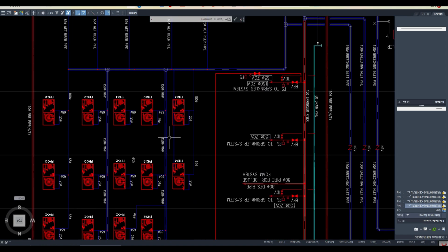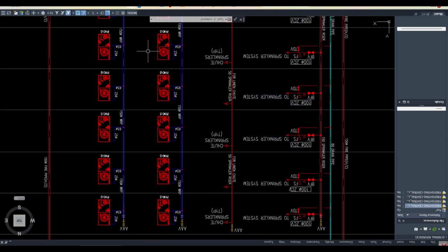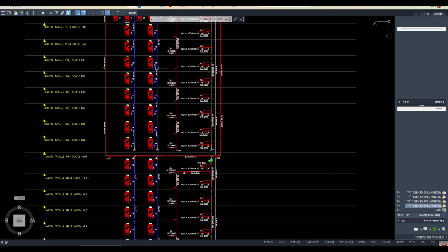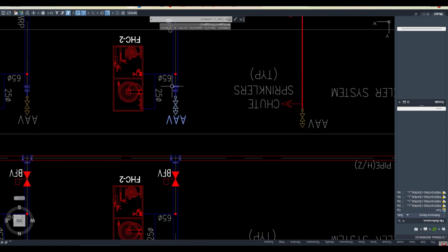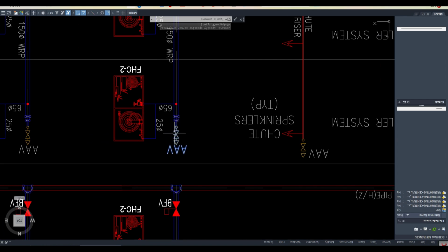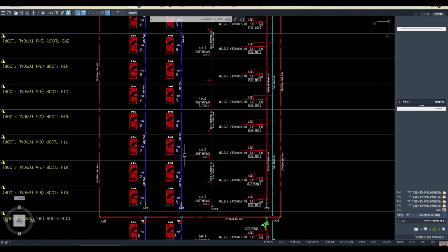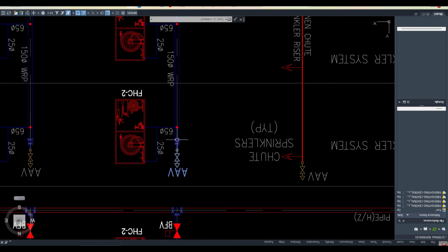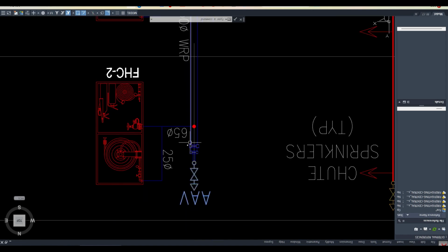The pipe size being understood, not less than 100 mm, and the pressure of the remotest location should not be less than 6.9 bar. Okay, and then at the top of each riser you have to keep the AAV, automatic air vent, which will act like an air vent. Why? Suppose anytime when you clean this pipe, like at maintenance time, if you need to remove the water from there, then it will not go back, because if everything is already filled and you are not giving air to come back to fill the space, it will create a vacuum, negative pressure, so it will not allow you. So you need the AAV.